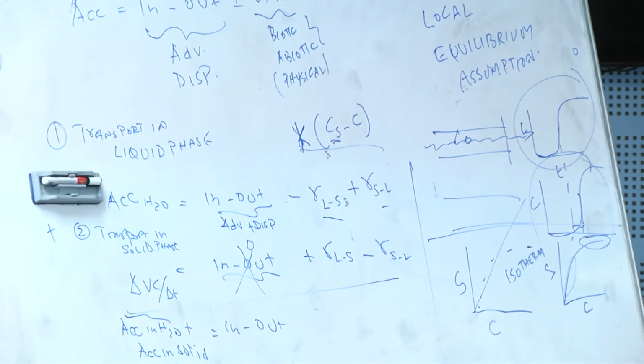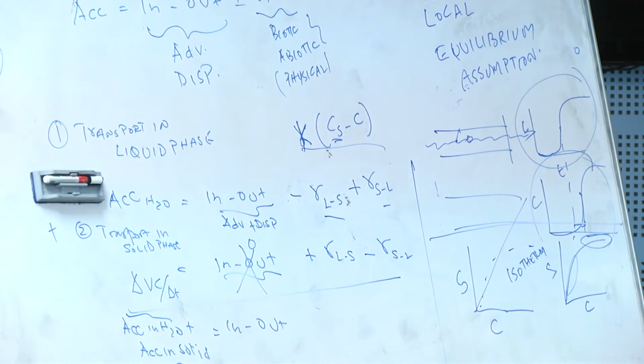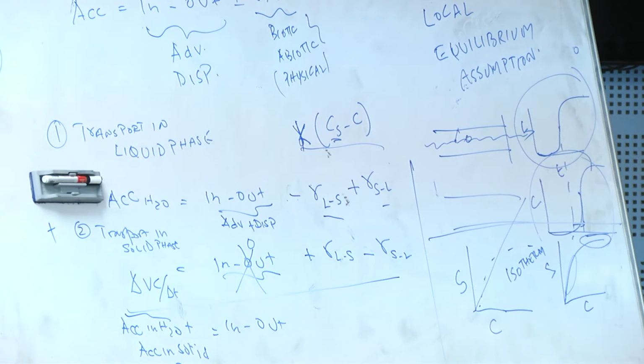On the other hand, once the parking lot is full, you have lesser and lesser chances of getting a parking spot, and when it becomes completely full, you have nothing to do but get out of that parking lot and go somewhere else. So, that is what the site limitations do. Okay. If you have site limitations, concentrations in the water phase will be much higher than concentrations in the solid phase. So, modeling that is important, because that would mean that your system is not removing or retarding that chemical as it would.